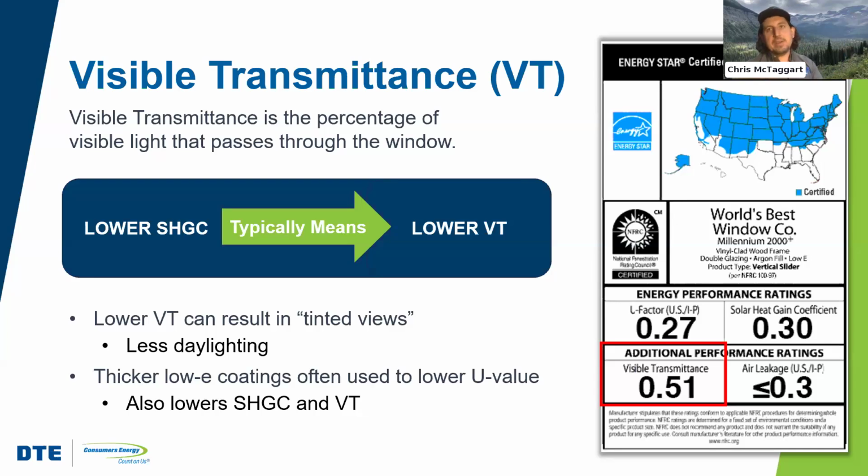So I ended up not going with that triple pane window, and I found a double pane window that performed just as well in terms of U factor performance, but with a modestly higher solar heat gain value, and more importantly, with a better visible transmittance. And so I'm overall a lot more satisfied with my windows because I was a little bit more thoughtful on how I selected them, considering all of these values that go into affecting the quality and performance of the window.